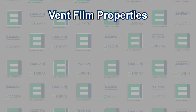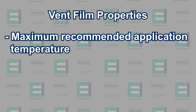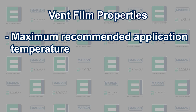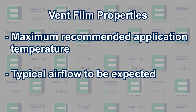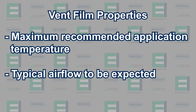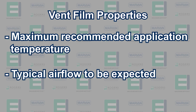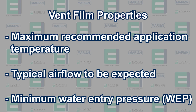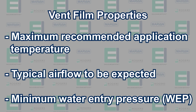The important properties of the vent film are, first of all, the maximum recommended application temperature that the film will withstand. Secondly, the typical airflow to be expected, which is measured in liters per hour per square meter at 70 millibar. And the minimum water entry pressure, or WEP, which is measured in kilopascals, or kPa.